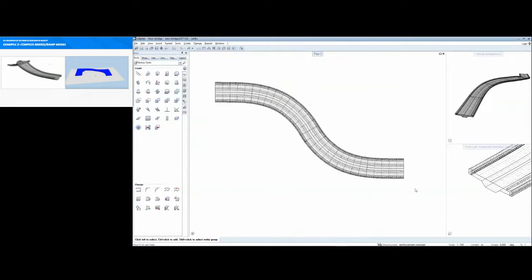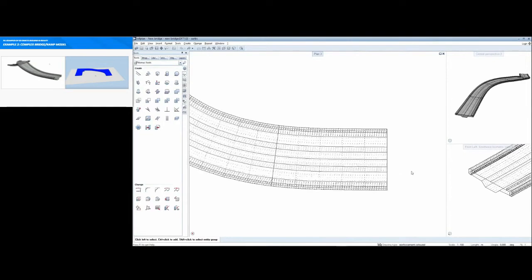Where a solid is created using the Extrude Along the Path tool, you then have a variety of options to edit it subsequently. For example, a bridge end can be marked through point modification and drawn out a little longer.